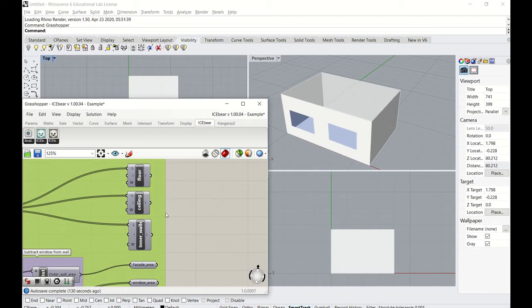Depending on what the boundary conditions are for the remaining part. If your ceiling is not facing outdoor, you basically don't need it. If your walls, inner walls it's called here, are not facing outside, then you basically don't need them either. But if they are facing outside, we need to have them in our energy calculation as well.